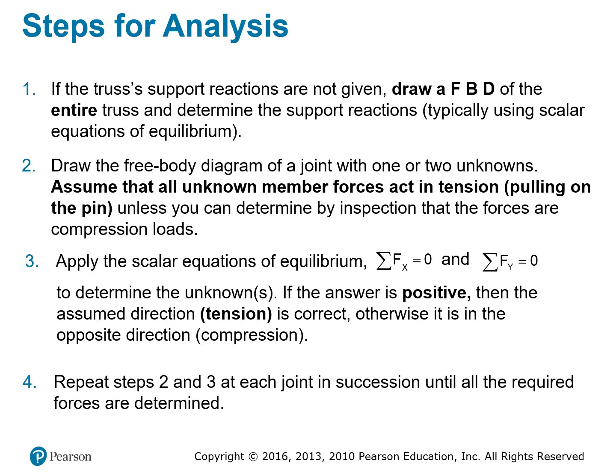Okay, so let's give you a general idea about the steps of the analysis. First, when you have a truss, you need to draw a free body diagram of the entire truss, because we want to find the supporting reactions. So the first step is to find the supporting reactions using the free body diagram of the entire truss.